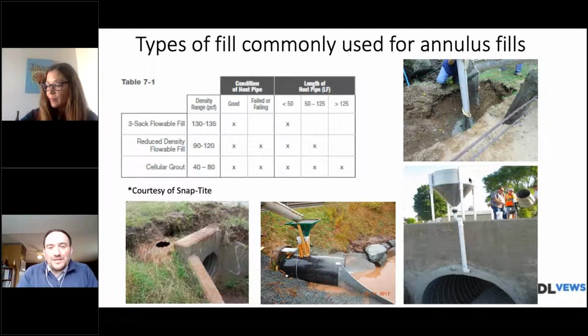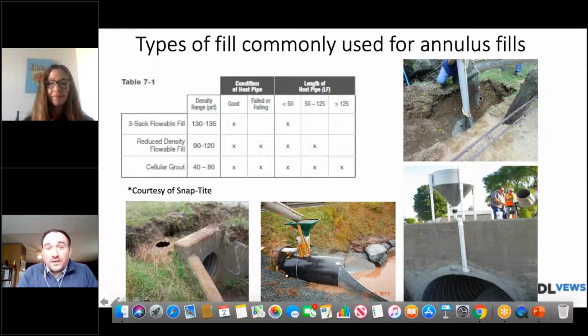Yeah, it's probably the single biggest concern when it comes to grouting of an annulus, right? Most of the time we have a provision for blocking the pipe against buoyancy, right? And then the question becomes, what kind of pressures are we going to put on the liner and or the annulus, and even the bulkhead, right? If you've got a bulkhead that's got a lot of lateral liquid pressure on it, that's something else that can and should be considered. And so to answer the question a little more directly, pressures can be exerted on a pipe in many different ways. Liquid pressure, head pressure, as we talked about earlier, right?